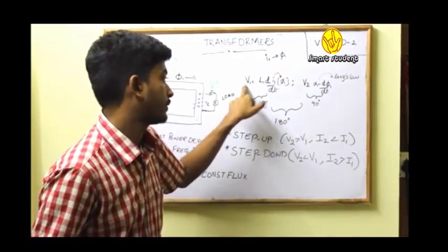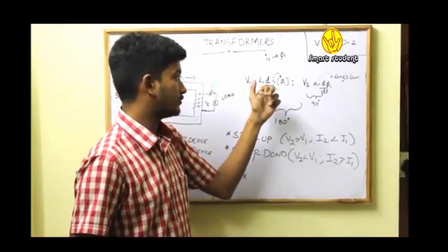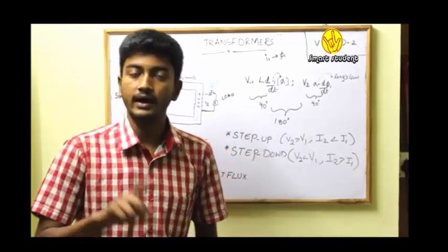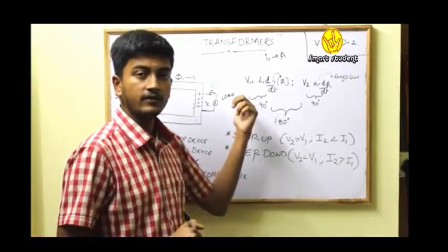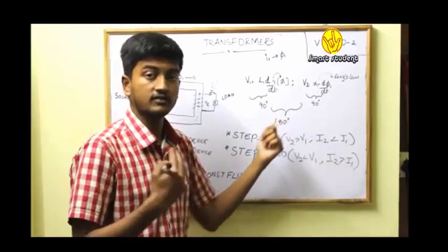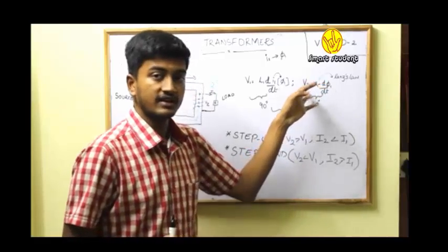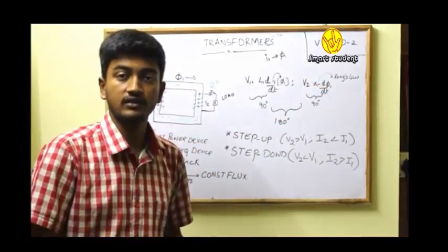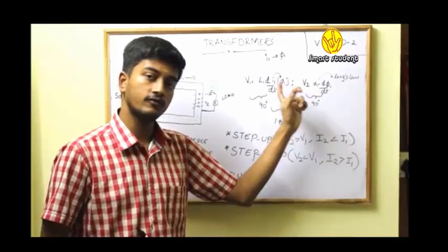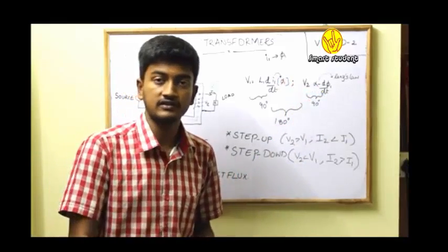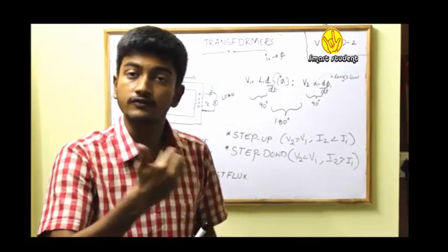The voltage V1, which is responsible for my current I1, we could relate as V1 = L1 dI1/dt, and we all know that the flux will be set up because of my current. The angle between my voltage and the current or the flux, more precisely, is 90 degrees. According to Faraday's law, the voltage induced in my secondary V2 is because of the flux produced by my primary circuit, and this induced EMF V2 is proportional to the rate of change of the flux linkages. We also know that according to Lenz's law, the angle between effect and the rate of change of cause is 90 degrees.